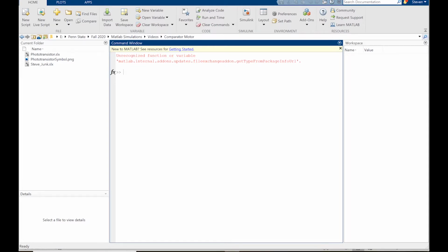It's going to be kind of like a Scantron, but I'm going to use graph paper, 4 blocks wide and however long. And so if you color in various blocks, it will send commands to an H-bridge motor driver, which will control the direction of the motors. So the idea being that you would write down a pattern of the sequences that you want the robot to go through, and that the robot will drive forward for a certain amount of time, and then turn left, turn right, stop, go backwards. And so you can sort of program a sequence in.